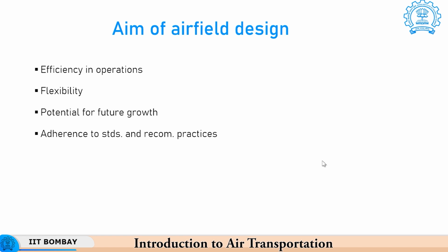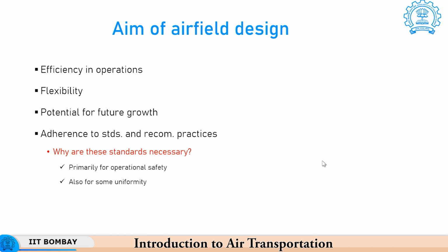Then we need to adhere to standards and recommended practices when we go for the design of the airfield. Now, you might wonder, why do we need standards? Why can we not allow complete creativity to come into play when we design the airport? The reason is twofold. One is primarily we want to ensure that the operations are safe, and in the process of trying to save the land or to optimize, you may cut corners and that may affect safety.